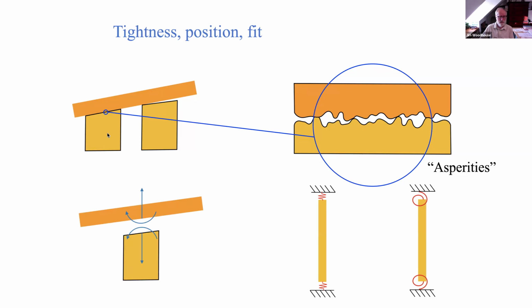Now, how does the soundpost communicate with the top? Well, basically, it could do two things. It can supply an axial force. So I've separated them and got blue arrows here for the forces. So there could be an upwards and downwards force. And it might also transmit a bending moment, at least if it's like the left-hand post and not the right-hand one.